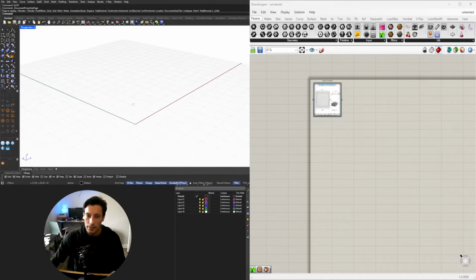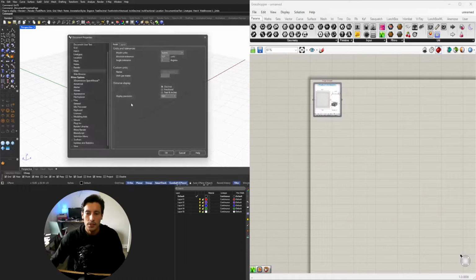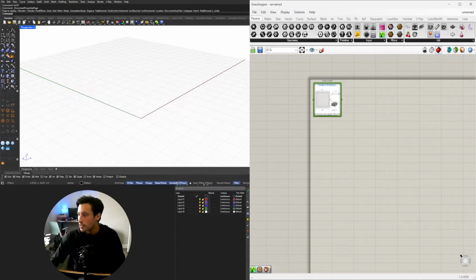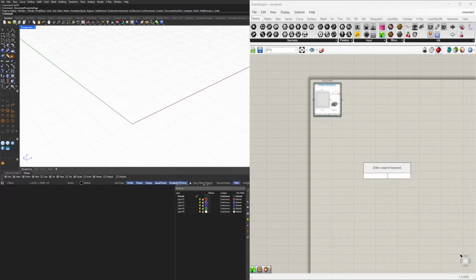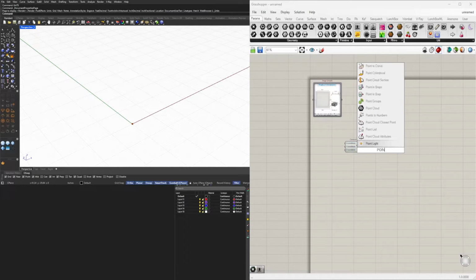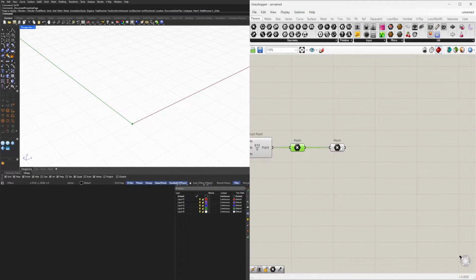Let's create this design. Now the first thing is the units. I'll be using inches. And so we have this. Now let's get into how this is going to be developed. The first thing that we bring in, if we want to change the location, we'll go to construct point. Then I like to bring in an empty point component because we can change that location if we use this. Now I do create another copy and then go like this. So we can work off of this one and then we can change this one if we want to.